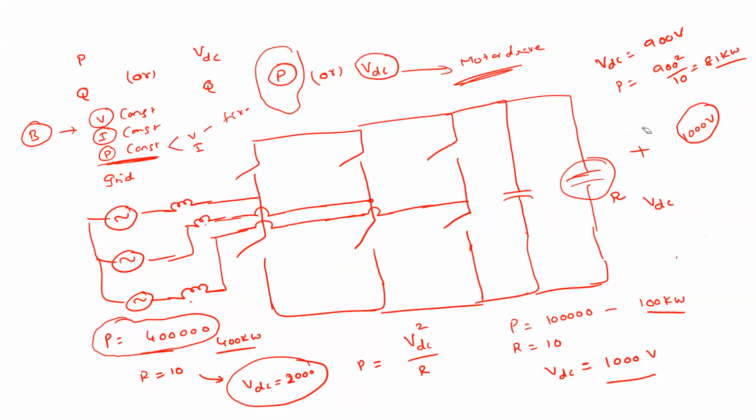So come to the reactive power. In most cases, we'll keep this reactive power at 0. Agree? If the reactive power is 0, and if the currents are controlled to operate at unity power factor or sinusoidal, then the inverter will operate at unity power factor.